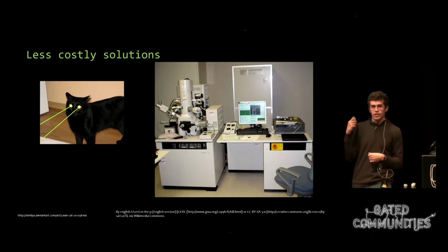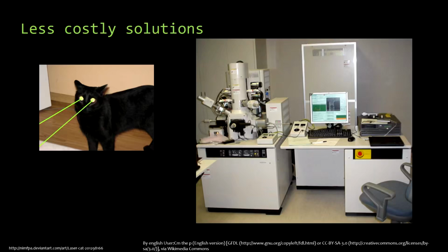This is a focused ion beam machine. It's a cool beast. It can take a chip that's already been fabricated, and it has an electron microscope in there. It actually shoots little ions into it, and it can rewire small parts of the design. Can't do major things, but you can do small things. This is done on a per-chip basis.